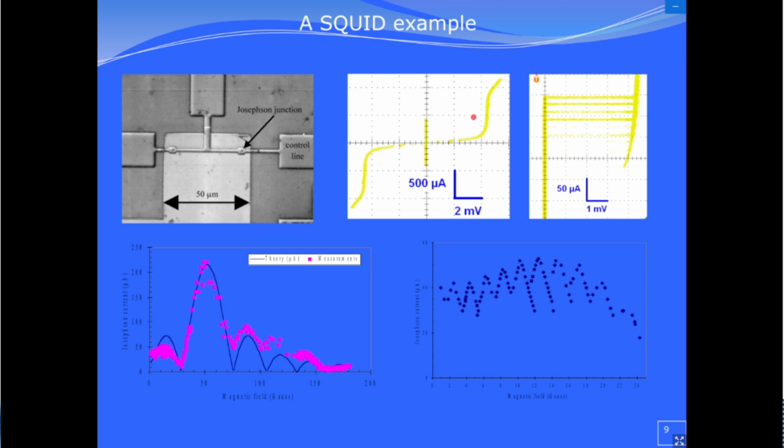If you go higher, you will switch, you see the gap voltage, the beginning of the linear part, and of course the junction is not perfect. There are sometimes some pinholes inside, or some cross tunneling, which is not quantum tunneling, and you see some leaks here, like a large resistance in parallel. A good junction should be better than that, but this one is not too bad already.